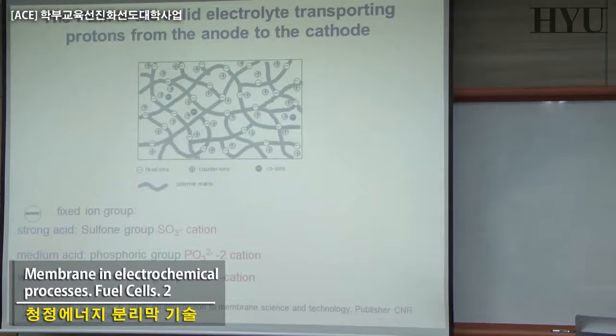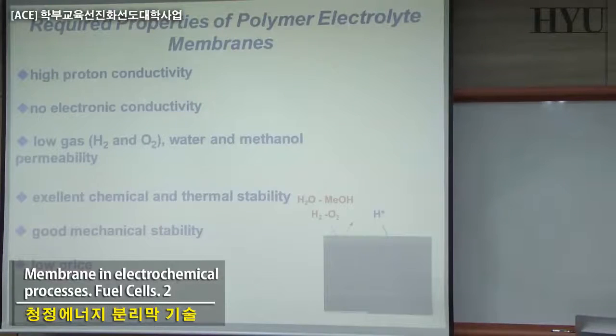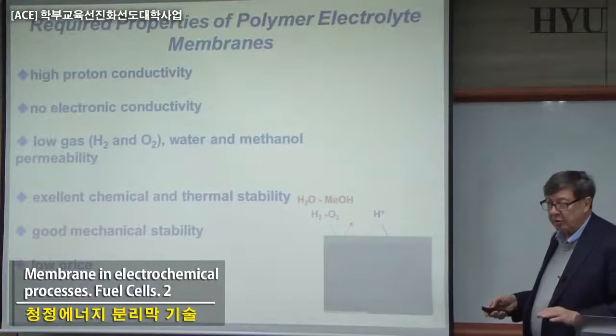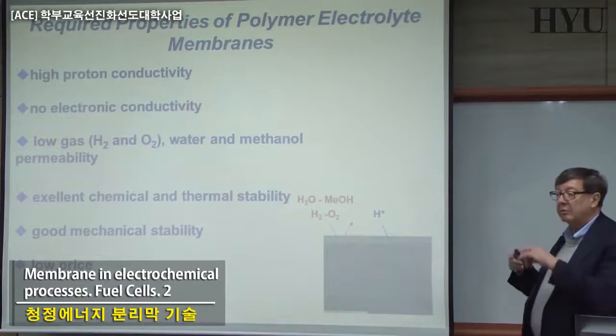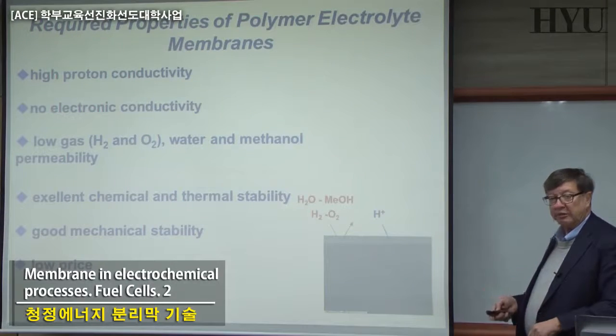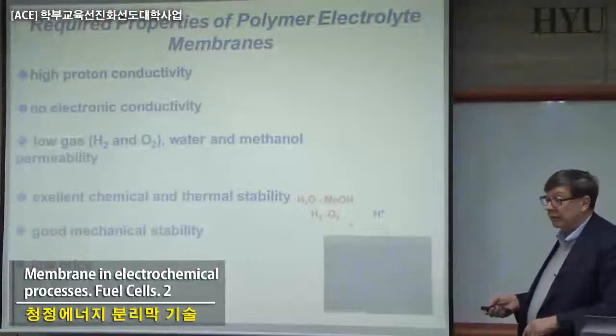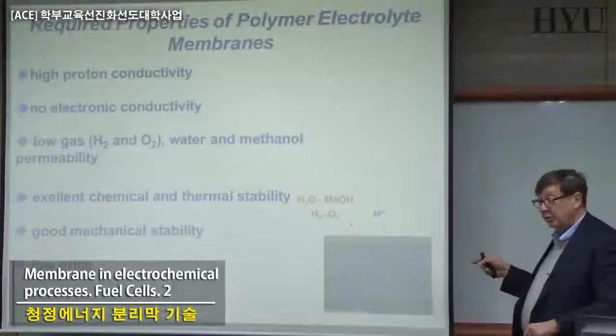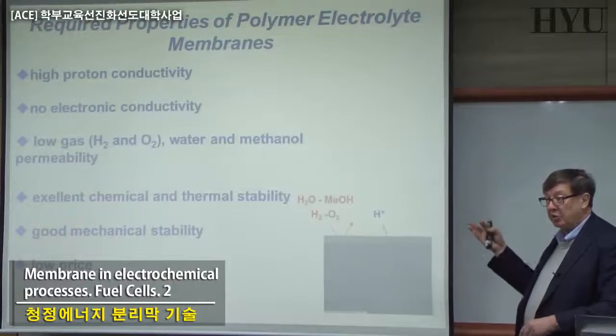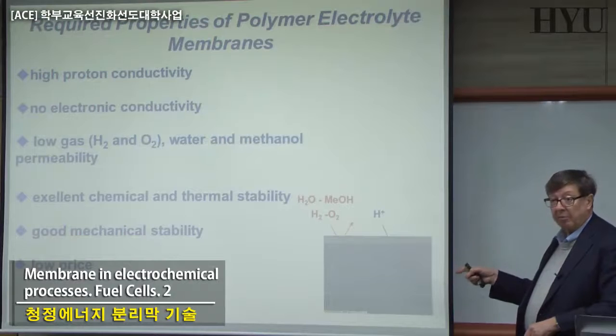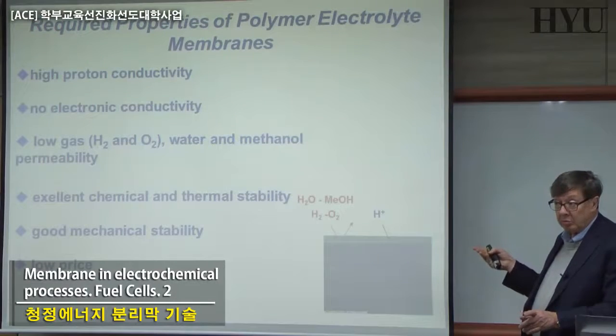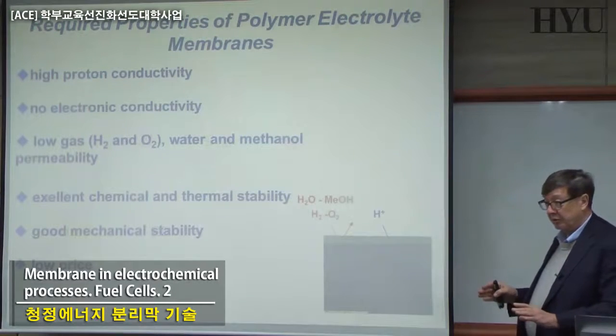And we already described, when we were talking about nanofiltration, how the system really works in terms of Donnan exclusion. Donnan exclusion is the phenomenon that controls the mechanism of transfer of these ions. Depending on the charge density of the polymer, you know at which concentration you can have a transport number approaching 1; the transport number is not a constant.